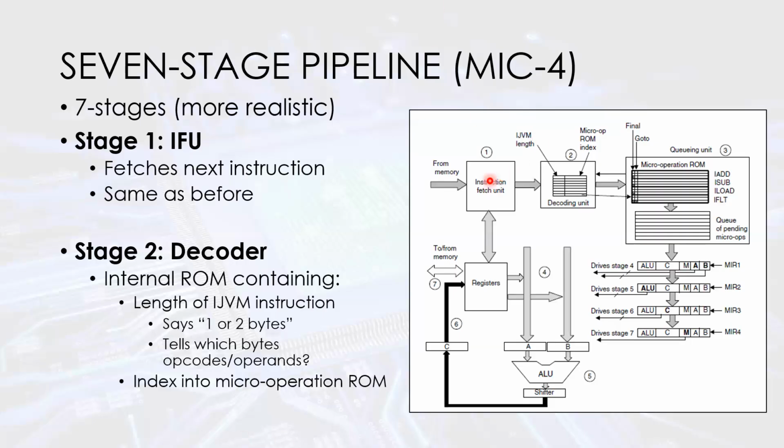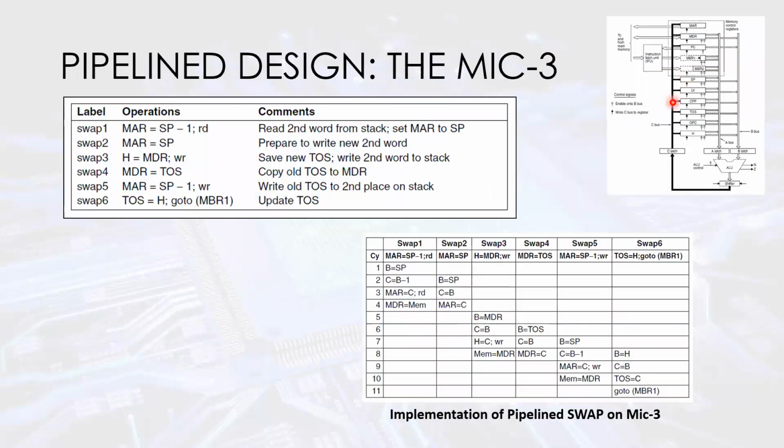Okay, so if we look at this graph, down here is the main thing we've been looking at, right? We have registers, they go out to the AB bus, the ALU goes to the C bus, and the C bus writes back to the registers, and here's our to and from memory. This right here is the control store, that block that we talked about being in the top right. This is the instruction fetch unit, which, if you recall, in the last slide was kind of hanging off over here, right up onto this side.